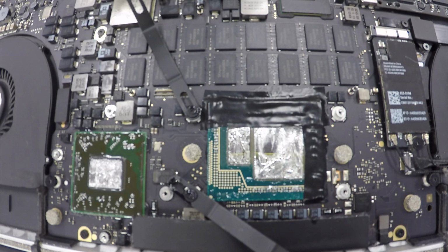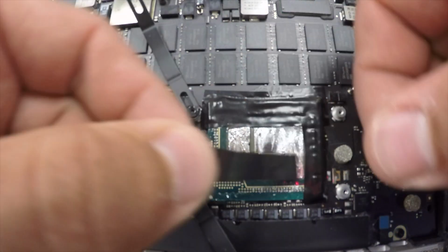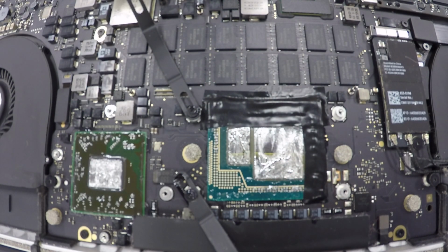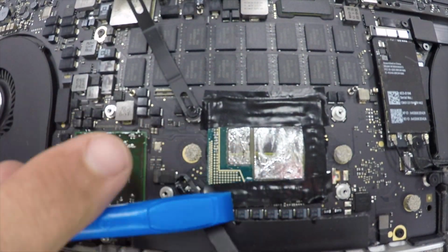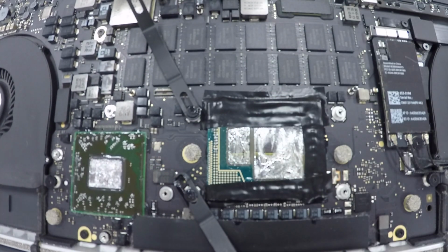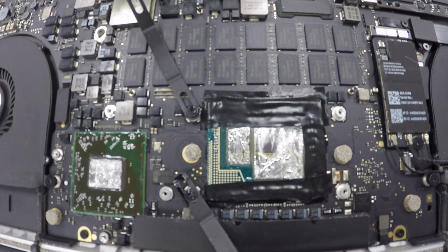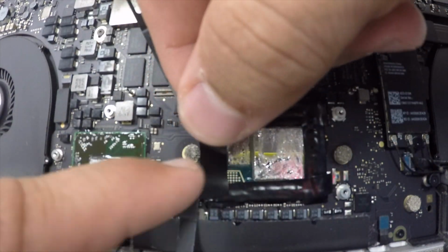Now I will soak up any excess liquid metal with another Q-tip if there's a lot of puddles on the surface of the CPU and GPU. Now a little tip: use calipers and measure the exact length and width of electrical tape you need, so it makes it easier when you're cutting it. And then you're going to want to take that blue pry tool and push up against the electrical tape onto the board and the CPU edge, so you make a real good barrier so liquid metal can't move around on the CPU and GPU.